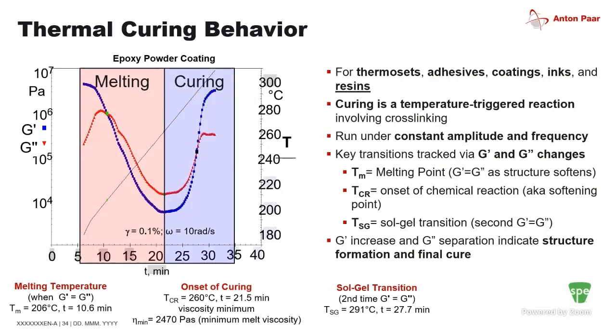As I apply more heat or more energy, the curing response gets faster and faster until eventually, with the black, I see what we call a sol-gel transition, where the sample transitions from a liquid to a solid. It's the opposite of melting, except we're now talking from a curing standpoint because the cross-linkers are triggered by the increased temperature. Then as I go to higher and higher temperatures, eventually the reaction stops or slows down because everything is fully cured.